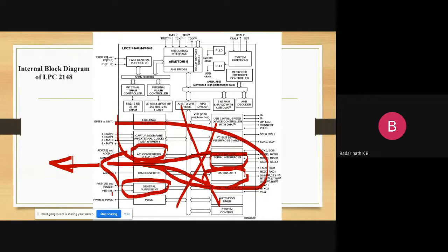As I said already, there are 4 alternate functions. The first function of any pin is always GPIO. So even if you don't write into the pin selection register, by default it will be GPIO, the first function. Now I have configured every pin for GPIO using the pin selection register, by default values. Now I have to start using these pins to connect the LEDs, keys and switches.